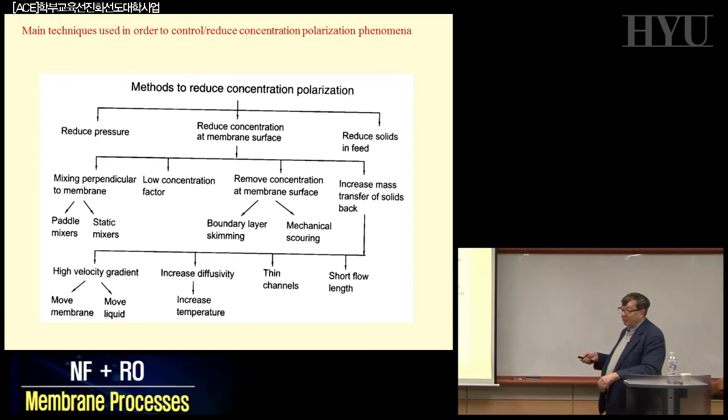If you want to increase the pressure, you can, but you also have to increase the cross-flow velocity in such a way that you mix more than before. Otherwise, there will be just a negative effect. So be careful. You have to reduce the pressure. If you reduce the pressure, less salt will accumulate, and you just have less concentration polarization. So it is just the opposite of what people were assuming on the basis of the equation I told you, which was wrong.